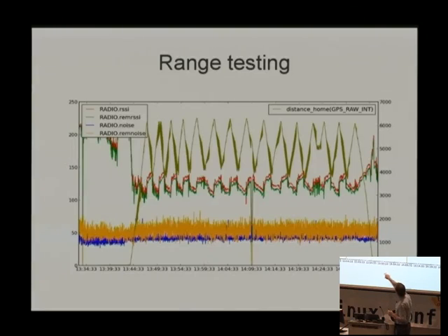And then you can see the noise levels. The blue one is the noise on the ground station, and the yellowy orange one is the noise in the plane. So you can see we have a bit of a noise problem in the aircraft. It's mostly the electronics, the Panda board, the Linux box on the plane, generates a lot of RF noise. We weren't shielded well enough. It still gave us plenty of range.